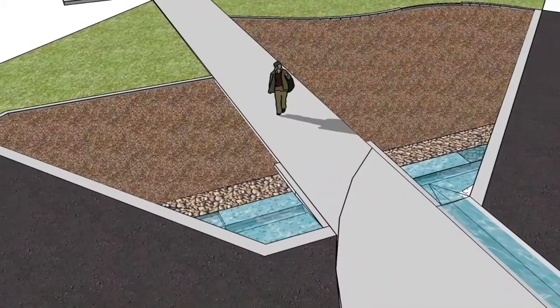Using EPA's SWMM software, we simulated a 2-year storm to gather hydrologic data and its effects on Oak and Washington. Our findings indicated that in an 8-hour period of a 2-year storm, the max depth of water would reach around 1 foot within the first hour, and the total inflow of stormwater would reach its max at approximately 60 cubic feet per second. The LID design we chose for Oak and Washington will be a sand filter.